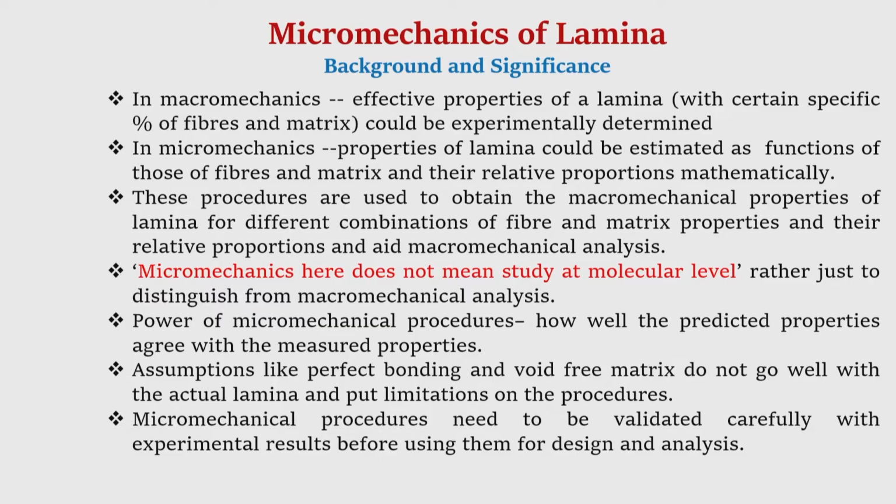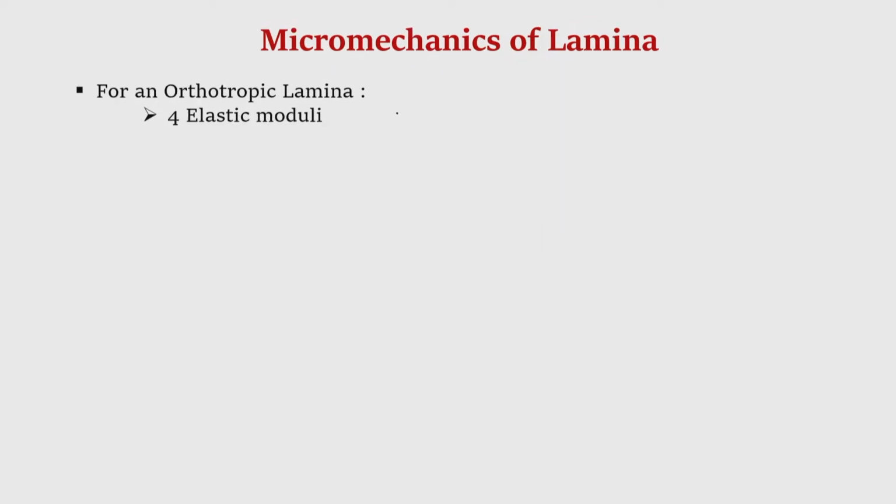Therefore, before using these micromechanical procedures for design and analysis of composite laminates, they should be carefully validated with the experimentally measured values. Only then could those relations actually be used with confidence. With reference to an orthotropic lamina, we have 4 elastic moduli.